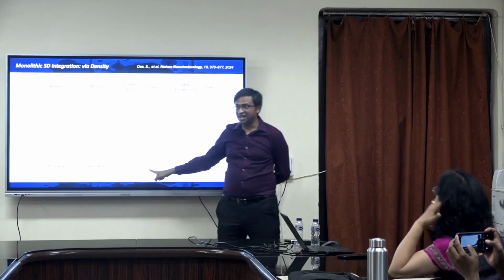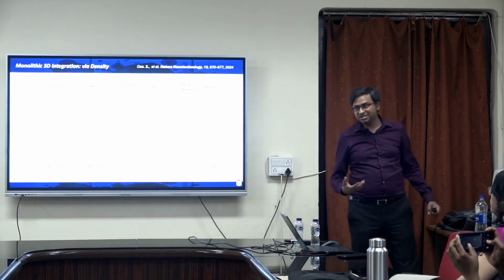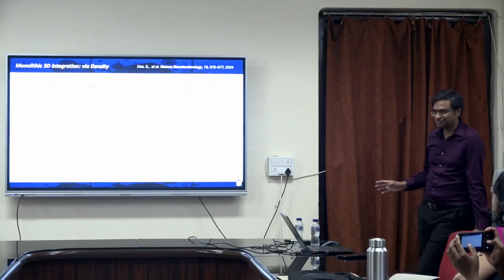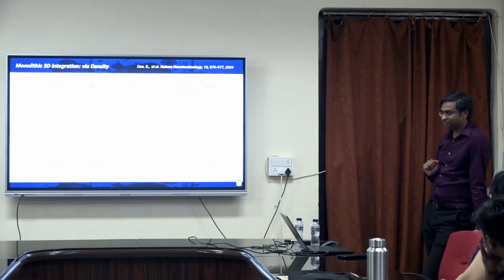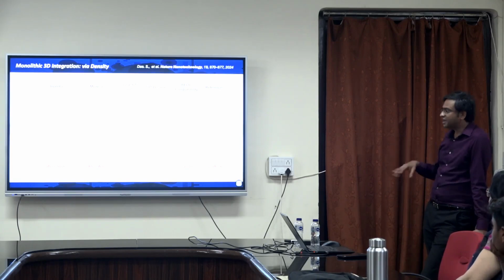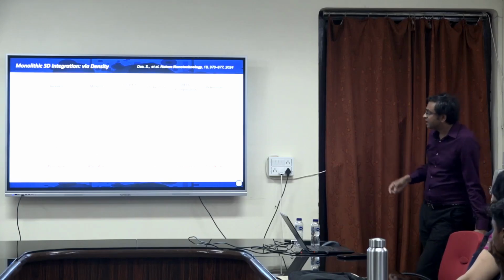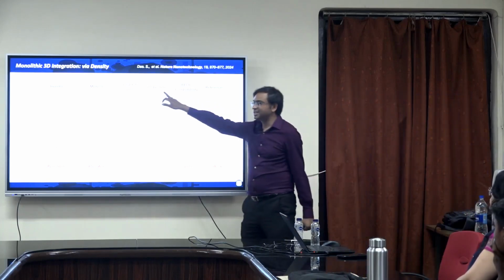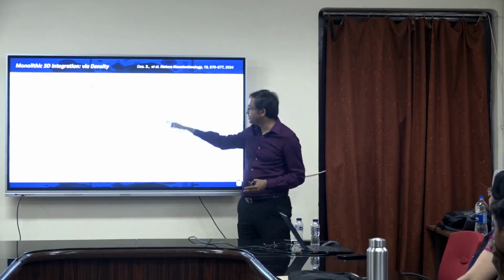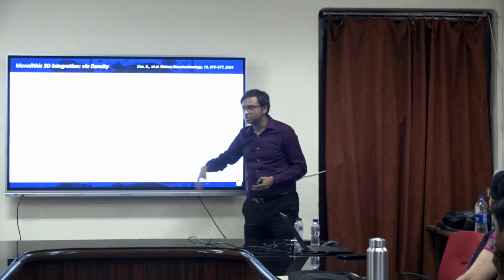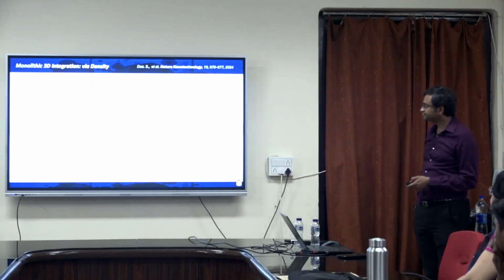And we are just starting in an academic institution with this number. This is not even generation 0 devices. So this is the power of monolithic 3D integration. One micrometer, in fact, now we have gone down to even 300 nanometer vias. You can see this is the integration density, the number of vias, the number of connections you have per millimeter square, and you can see we are already as good as what is happening with the heterogeneous integration.